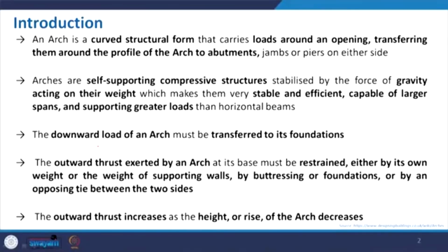Coming to the definition, there is no such distinct definition. So let us discuss what exactly the arch is. An arch is a curved structural form that carries load around an opening, transferring all the load through its profile. It is not given by a connection. So this curvature itself is transferring the load of the profile of the arch to the abutment, the support or the jambs or the piers.